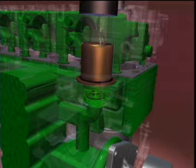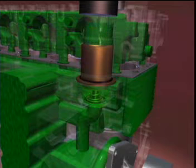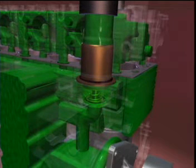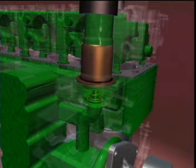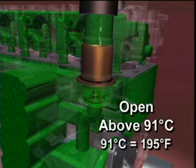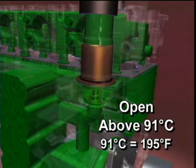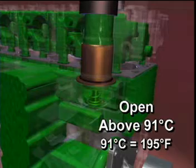As the coolant temperature increases to 82 degrees centigrade, the thermostat starts to open, and coolant flow to the bypass begins to be restricted. When the engine operating temperature increases to 91 degrees centigrade, the thermostat completely opens, blocking the bypass passage to the water pump and opening the outlet to the radiator.